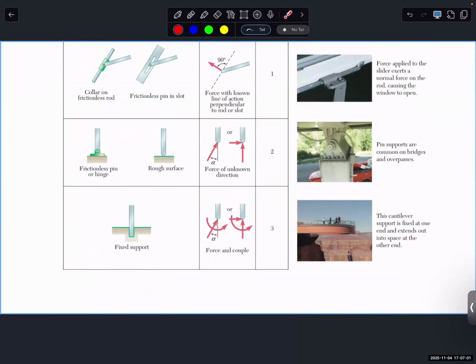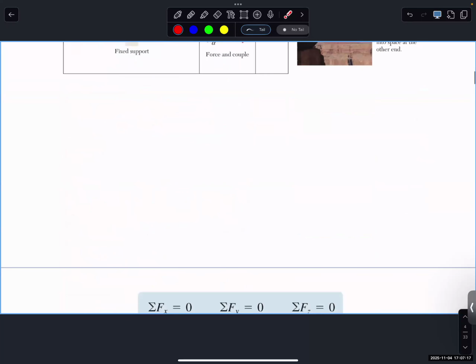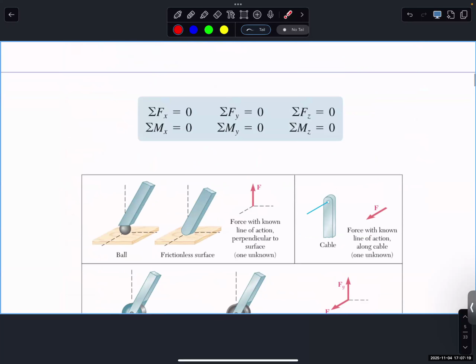So for this one, it means that for the reaction force, the bone combined with the PDL can provide the force in X direction, force in Y direction, and then a moment to keep your tooth in equilibrium. So this is if we simulate things in a 2D situation, and of course, in real life it's 3D. So basically your tooth can have translational degrees of freedom in X, Y, Z, and it can also rotate about the X axis, Y axis and Z axis. So 6 degrees of freedom, we have 6 equations.